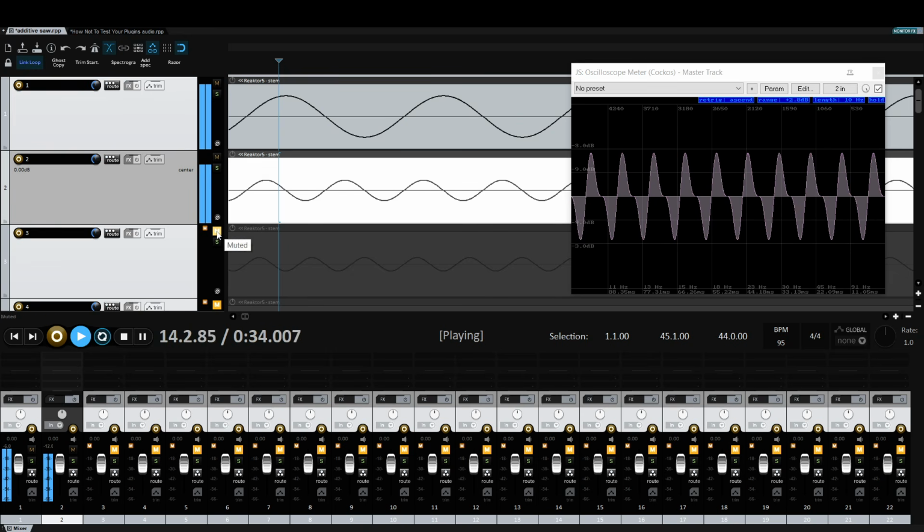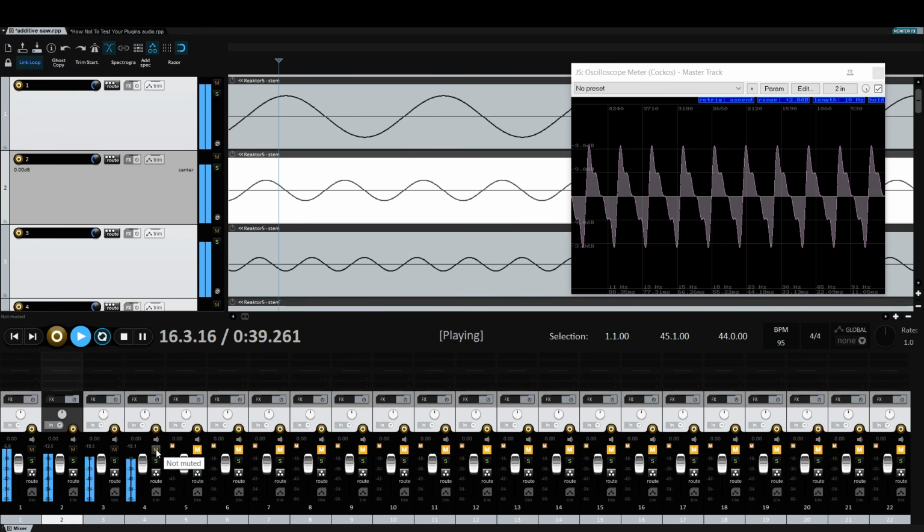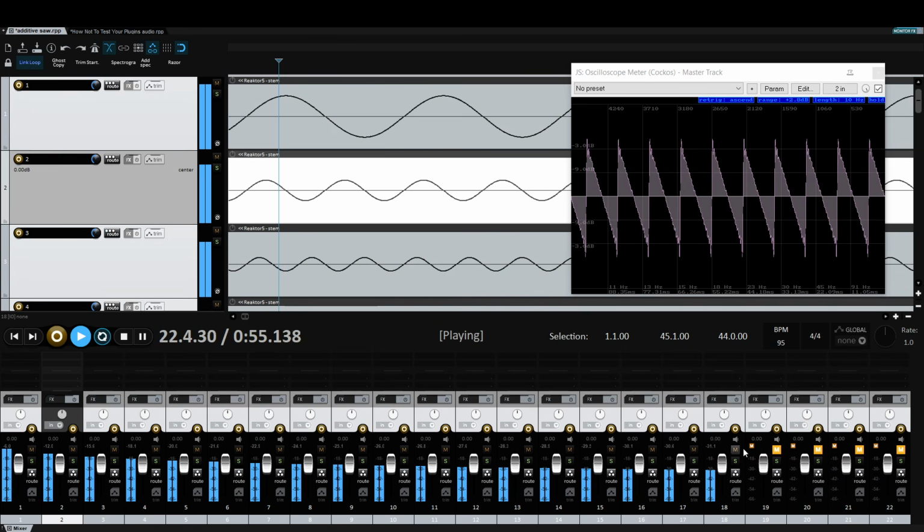So let's add another 300 Hz and 1/3 of the amplitude, 400 Hz and 1/4 of the amplitude, 500 Hz, 600 Hz, and so on. And we're starting to see that the more harmonics I add, the closer we get to a sawtooth in shape. A theoretically perfect sawtooth has harmonics extending to infinity, but that never happens in practice, of course. A perfect digital sawtooth will have harmonics extending up to the Nyquist limit at half the sample rate, and absolutely nothing beyond that, because it will reflect down as aliasing if so.